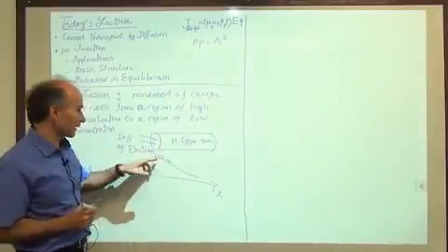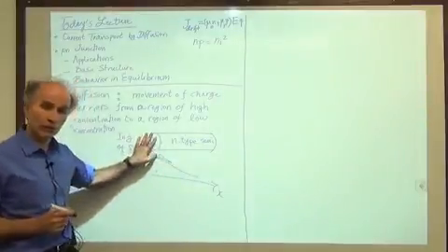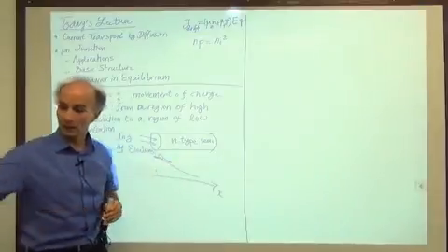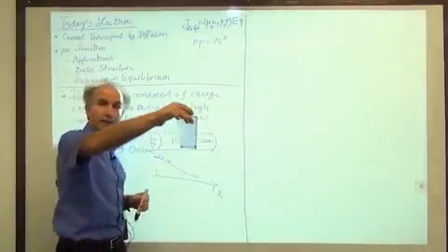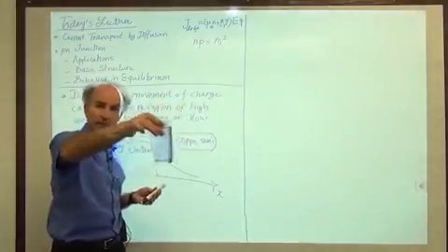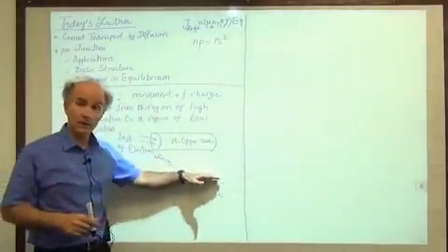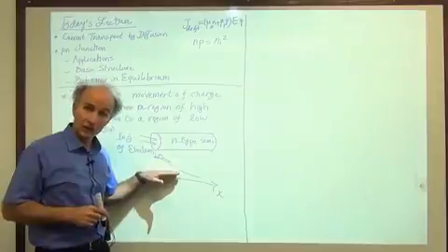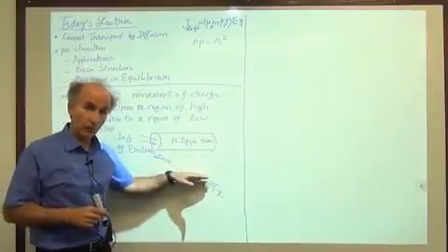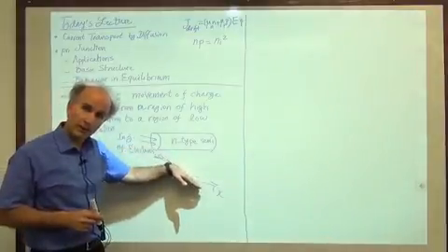You can imagine that if the concentration is constant from here to here, let's say there's no injection, there is no diffusion, right? The ink has completely diffused and there's no more tendency to diffuse anymore. So if the concentration is constant, if the gradient or the slope is zero, then there is no more diffusion. So it must be proportional to the slope of this concentration.